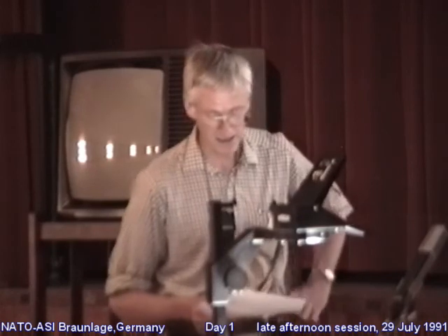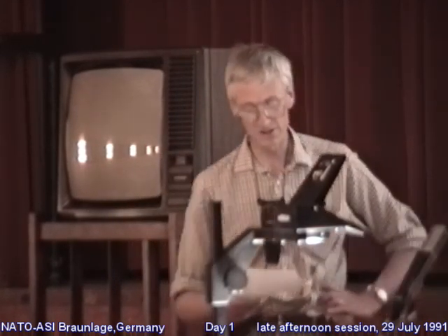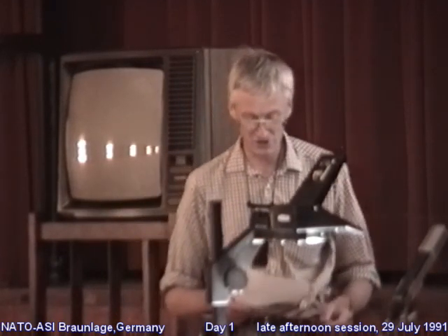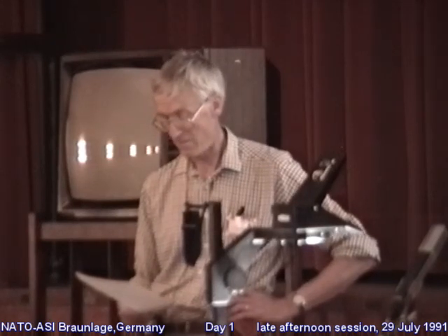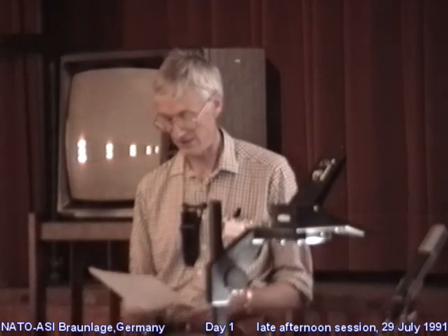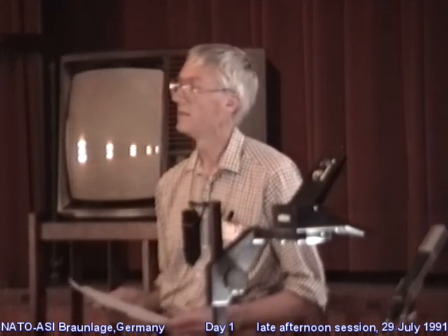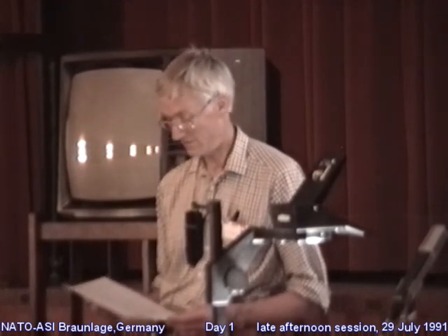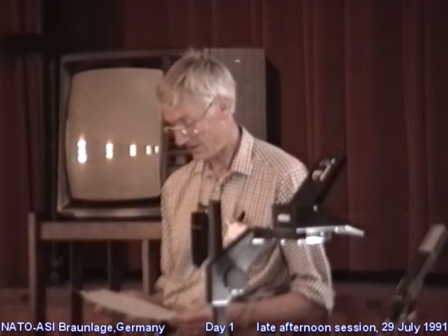And as we'll see later this week, instead of true sliding, we can have shearing or tearing, if you like, of the metallic microjunctions that result in the first place from the gripping action of intermolecular forces. In which case, any values of shear strength that we derive from analyzing friction experiments will very probably bear no direct relation to adhesion parameters. And as we'll see, this is because the energy dissipation mechanism involved is to a large extent involving bulk effects.